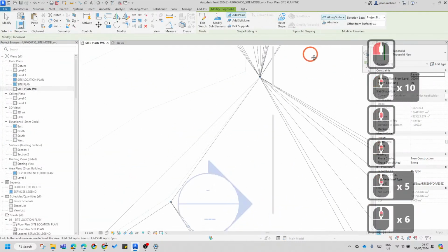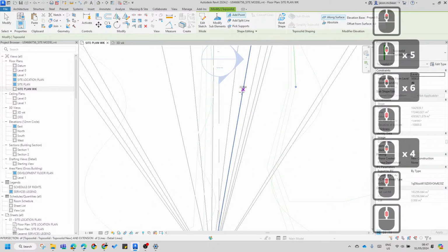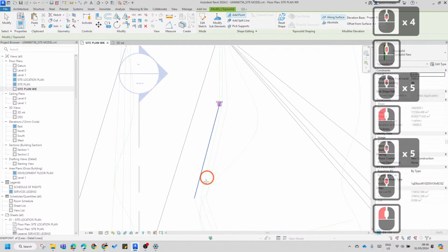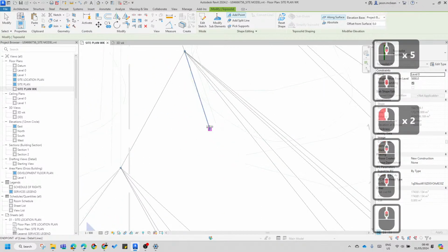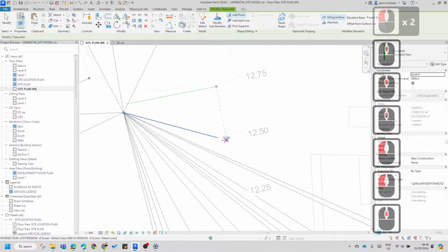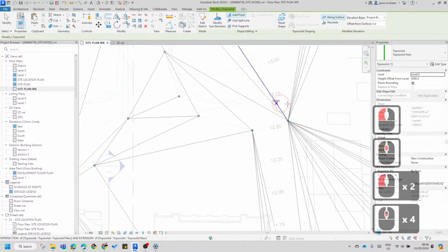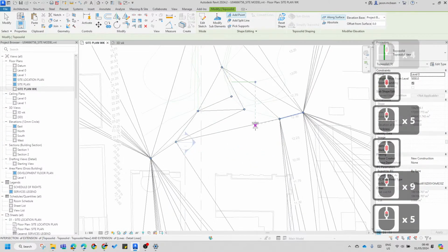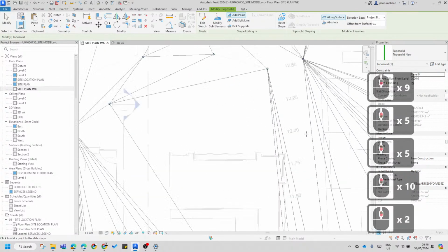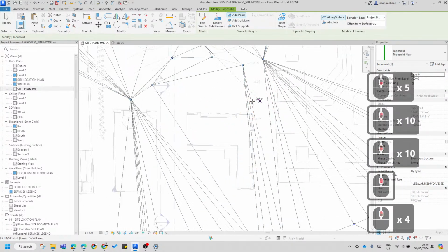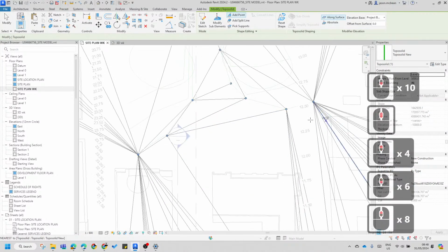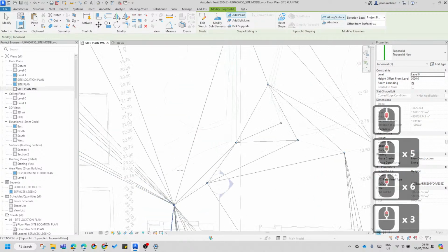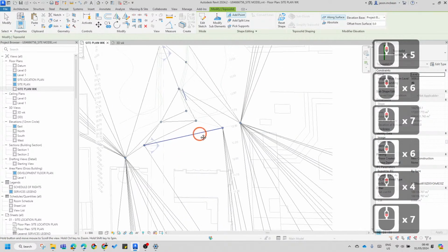So maybe that should be a nice thick red line so we can see it better. Yeah. Okay. But you'll see, this is quite easy. Once you get this, and what's nice is it gives you endpoints to snap to. And you'll see, all the time, it's just trying to make triangulation. It's trying to make triangles in which it works. So now, that's my first, now you can see it's created a bit of a flat spot here. Yes. Okay, remember I can go and add this line back. I might have to go and add that line back, but it's falling now. It's falling. So you might have to add another bit of line work here, but you can trace that very quickly. Straightforward.